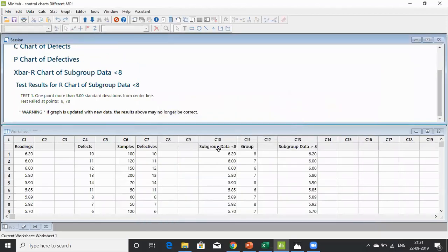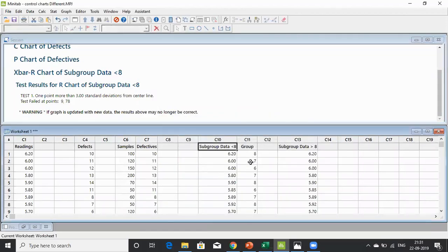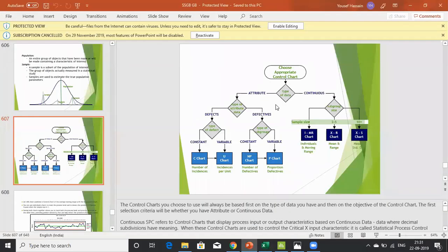It's quite straightforward. We collect a sample data, and then we'll see if there's any subgroup. Based on that, we select a decision of which chart is appropriate to use, and then we go ahead and run a control chart and see if the process is in control. And this is something which you can use even without a project, right? This is a hygiene that is used on a production or process floor usually.